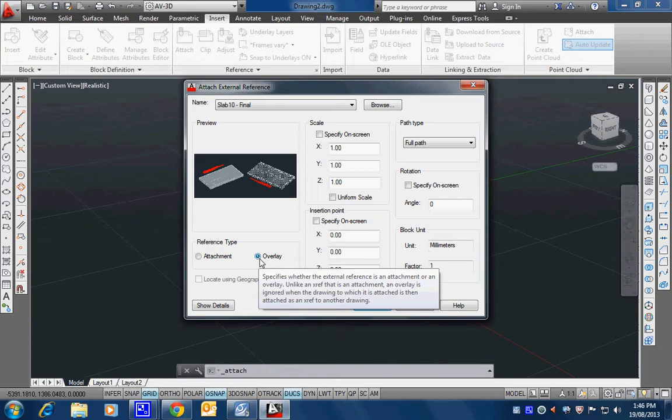Therefore, I need to have it in here, and I need to have it as a reference so I can work out where the perimeter is, so I can draw my walls, all right? So I need it. So I'm only bringing this an overlay, and it's only good enough for this plan. If this plan, called floor plan, gets externally referenced into my electrical plan, then all it will bring in is just the floor plan only, not the slab.